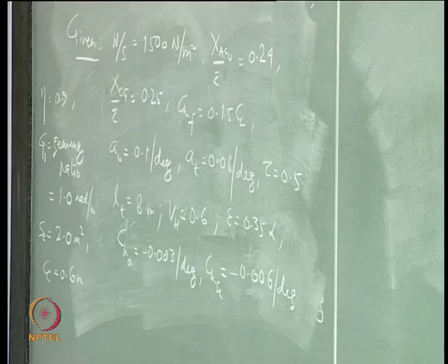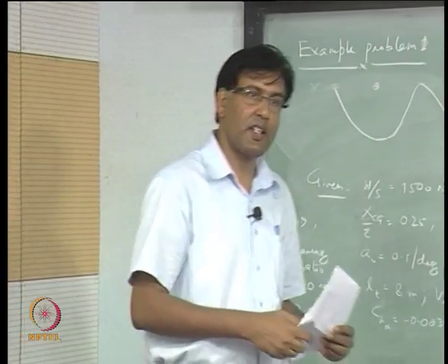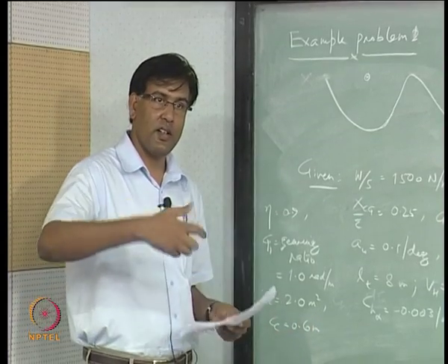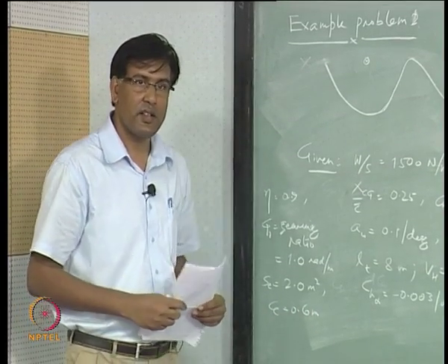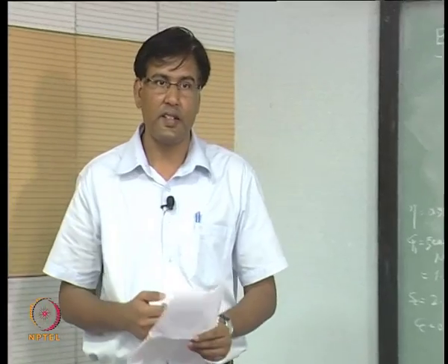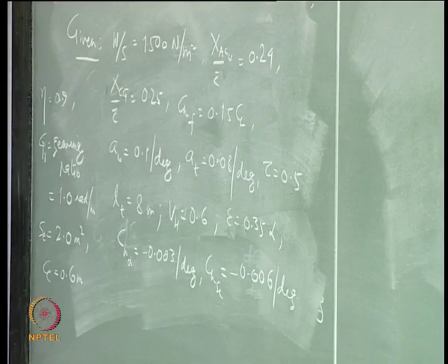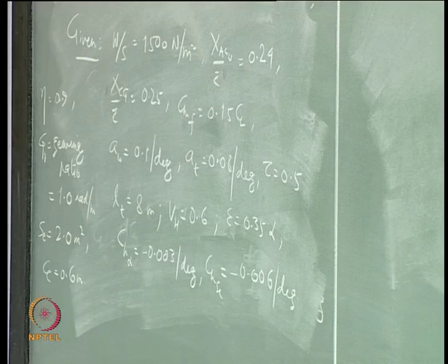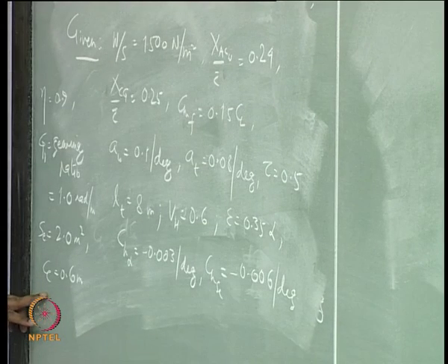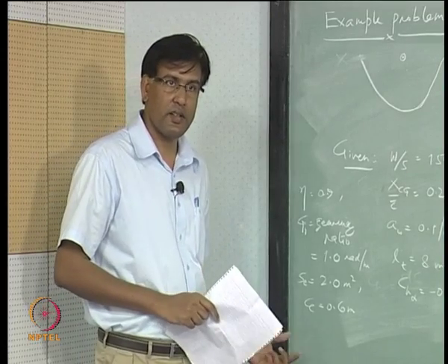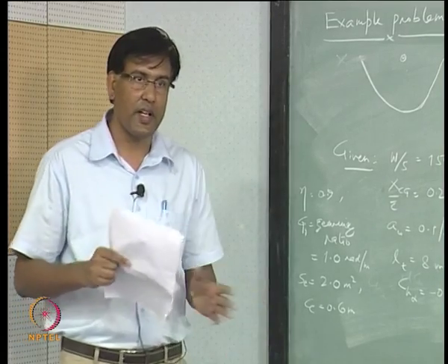You are getting, so you are deflecting the stick by some amount, and that is in meter, and that is going to rotate the elevator in radians, right. S_e is the platform area of the elevator part, okay, behind the hinge line. C is the chord which we are measuring behind the hinge line, right, chord line of the elevator.